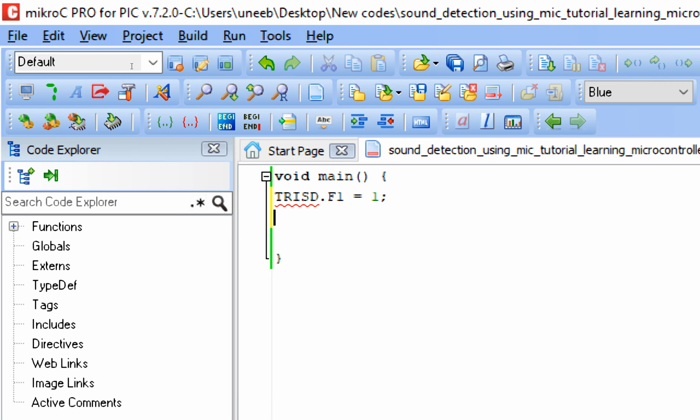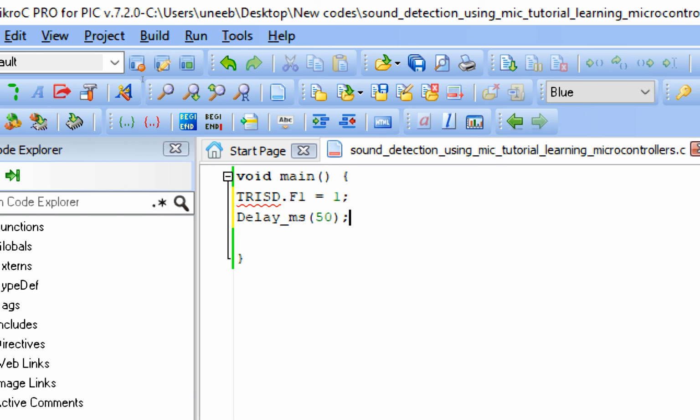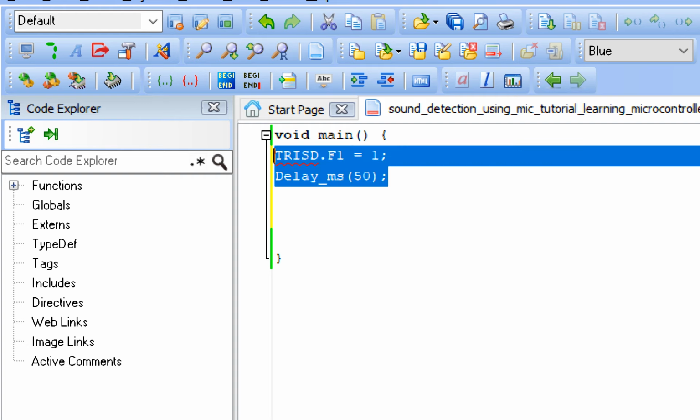Simple as that. Now, initial state, there is no need of the initial state. It's a sensor, it will auto set its initial state. We give some initialization delay, also not needed, but I always suggest you give it in the one-time loop for the smooth running of the programming. Now guys, we got our sensor pin initialized.